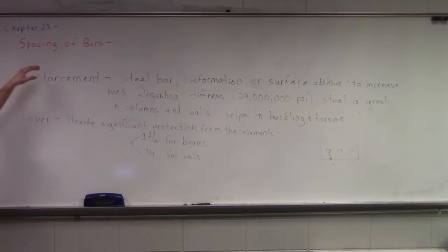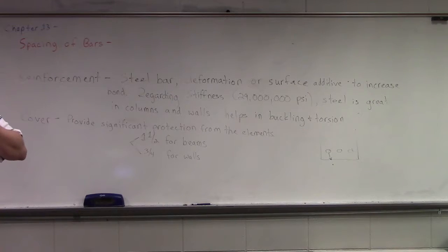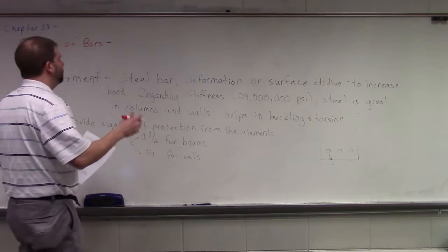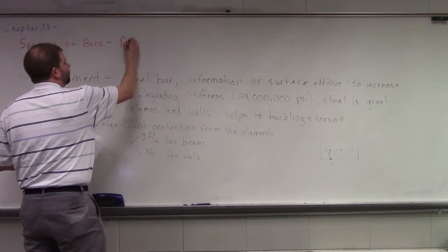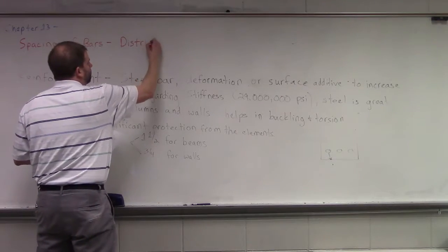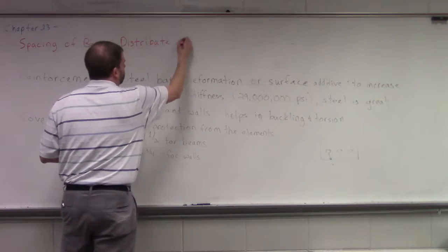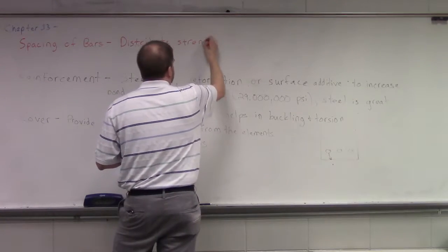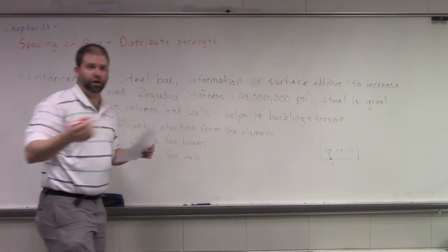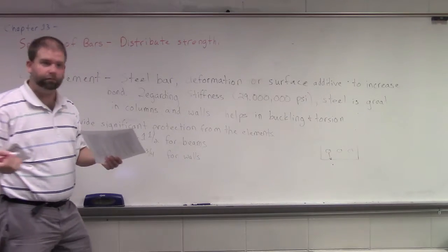Right. Why would spacing of bars be important to us? What are some big reasons? Just distributes the strength when the loads are on there. Yeah, we want to distribute the strength, right? We want to make sure that we don't have areas of unreinforced concrete, right?